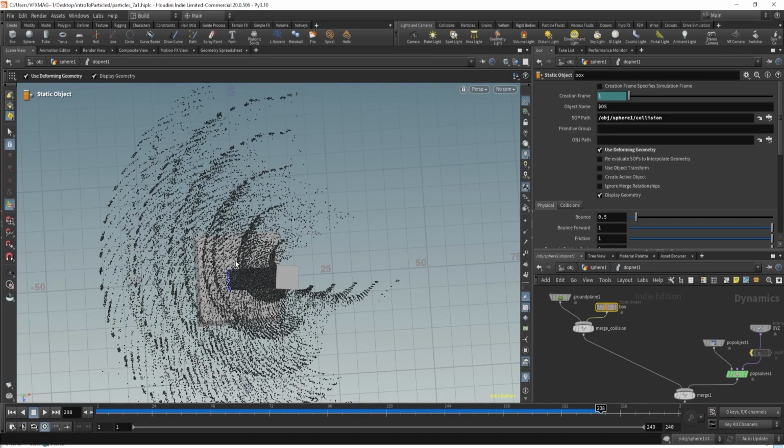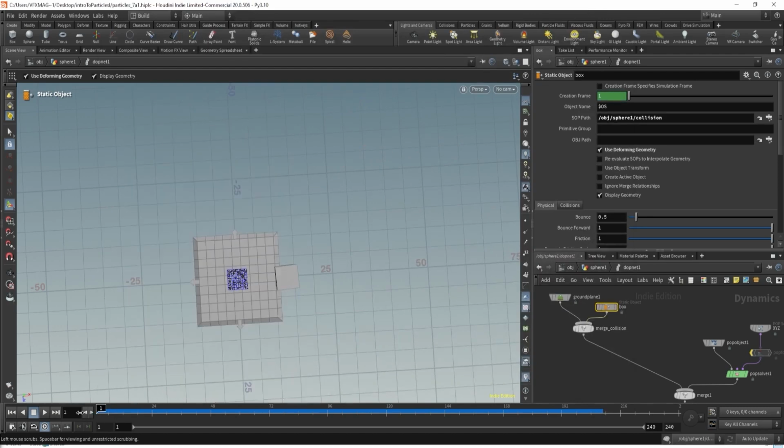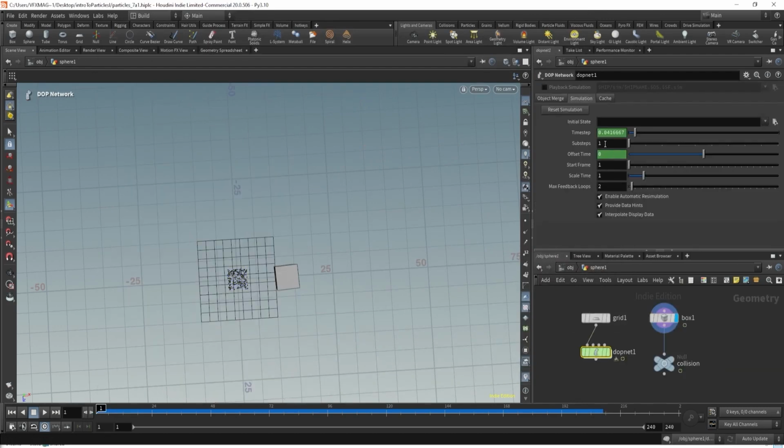First, let's understand the reason behind it. In this case, we need in-between frame data. For example, first frame, second frame and third frame. At the moment, the simulation is running this way, right? If the object is rotating this way, and this is the second frame, I want information in this area also. So we have to run this in between frames this way. And here we have to use substeps. So let's set substeps. If I increase substeps, will it fix it? Let's check it.